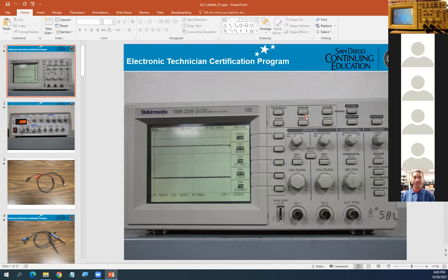Yeah, later on, keep going. Then when you want to press auto set measure, maybe after you move the probes, now the probe is already there. Oh, like on the volt division knobs, if you have to change them, then you're going to have to press auto set measure again to see where you're at.